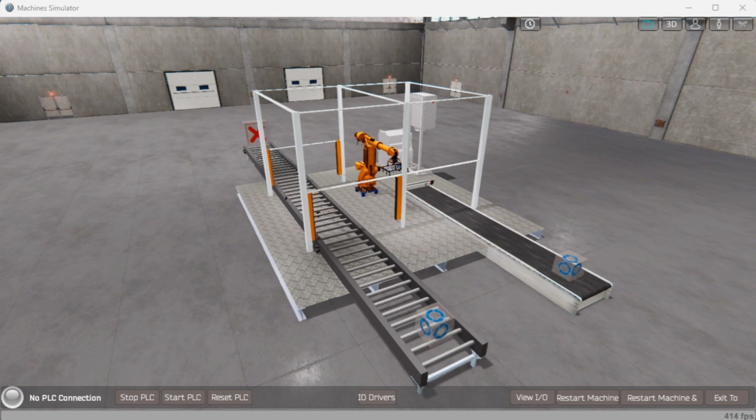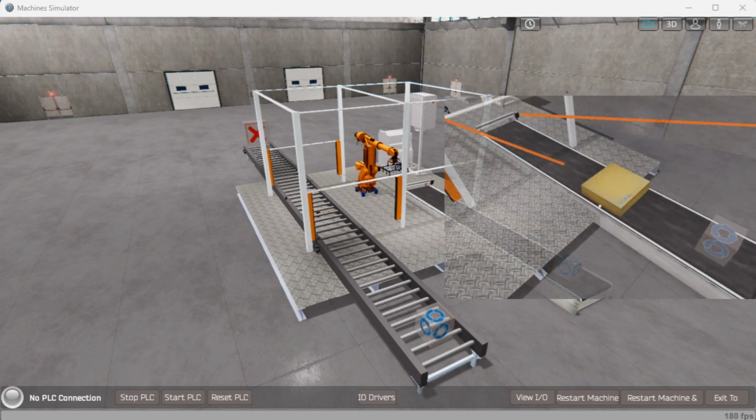The robot loader has 2 conveyors. The belt conveyor will contain boxes. It will operate when there is no photocell 2 signal. When the conveyor is on, it will automatically create another box. Photocell 2 will stop the conveyor from operating. The boxes will be created all the time while the robot loader is running.